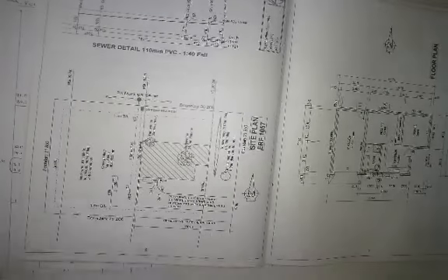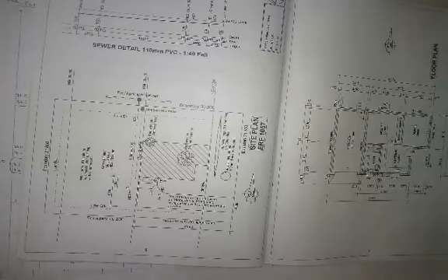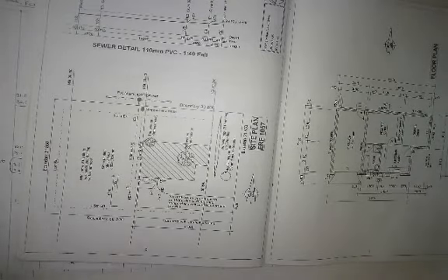Maybe just clear around the footprint of your house. Meaning they just want you to clear around here where your house is going to be. That means you'll just need to allow 1.5 all round for your working space. Remember, if you're going to need to put scaffolding around here, and put materials and stuff like that around the perimeter of the building, then you need some space. You can't put it exactly on where the works are going to happen. So you need to allow 1.5 for your space around your house, guys.